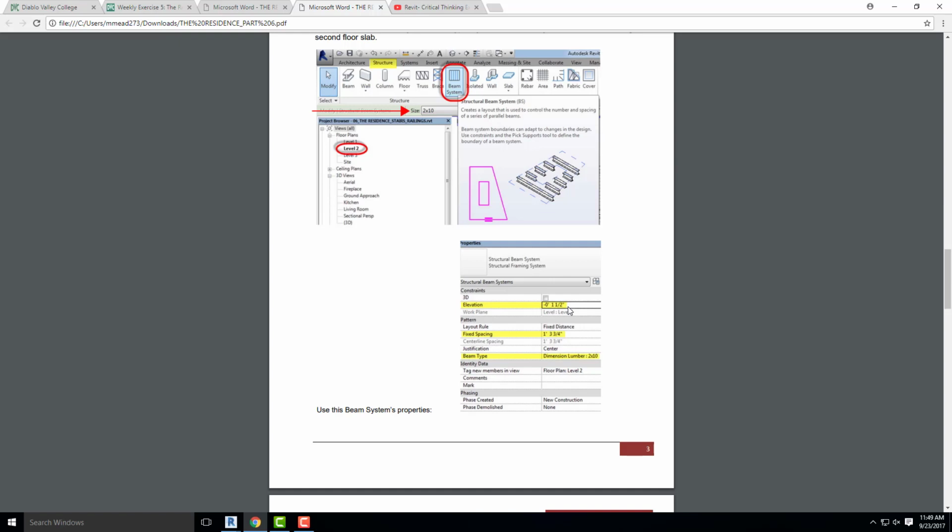That hardwood floor might be, we'll say, a 1/2 inch thick. And then our plywood, we'll say, is 1 inch thick. Okay, so that whole assembly is 1.5 inches. And then we have our floor framing, which will be below, which is like 6 inches thick or 8 inches thick or something like that. Okay, so that's why it says what it says.